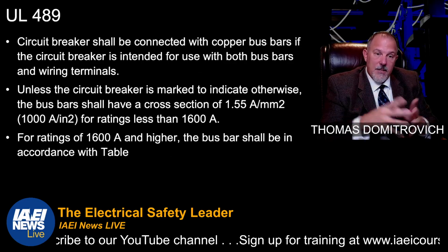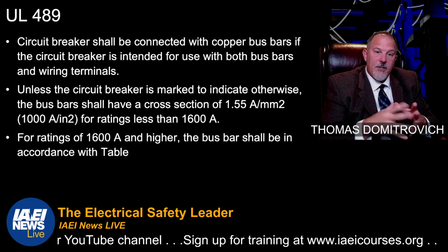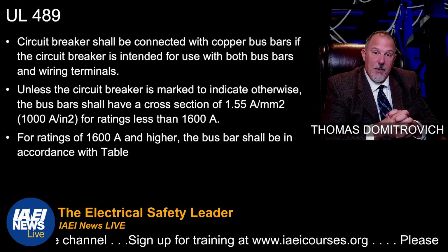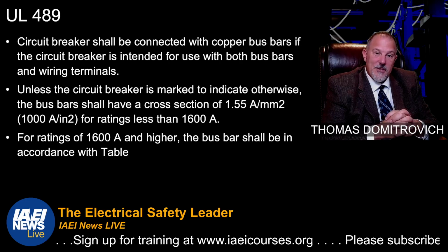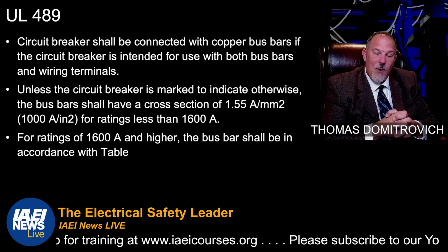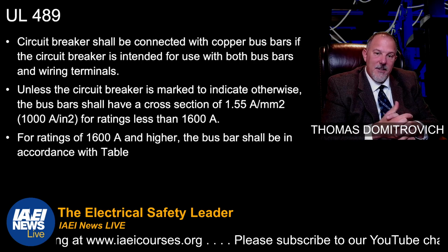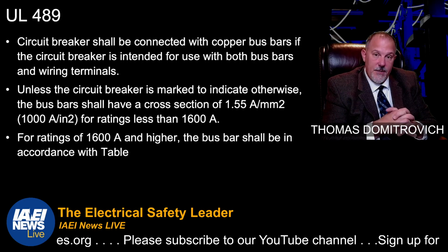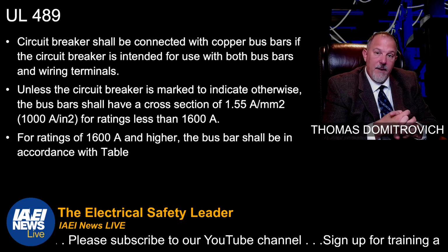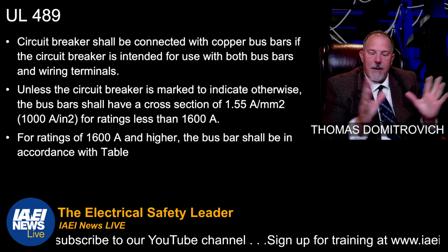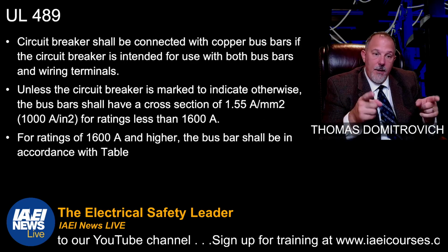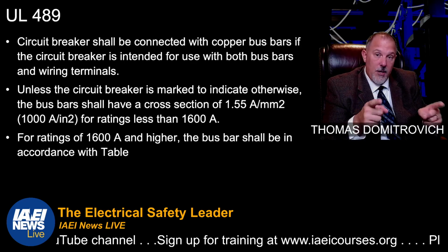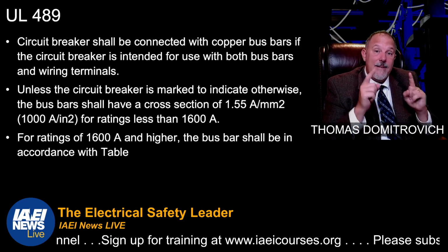Now look at this next one. Circuit breakers have to be connected with copper bus bars if the circuit breaker is intended for use with both bus bars and wiring terminals. So what does that tell you? You have a panel board and it's got aluminum bus, and you have a breaker and you want 100% rated, and you go, oh, I've got to go buy a new breaker. Your panel board construction makes a difference.